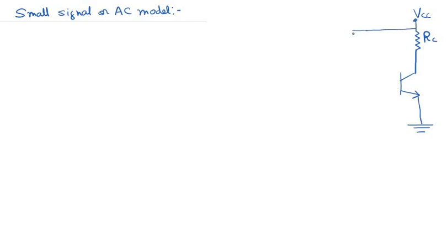We could have also done it with the voltage divider biasing scheme. There is not much difference, but right now we are showing this fixed biasing scheme over here. This is our base resistor RB, and just as before, the AC voltage is provided through a different path, where this capacitor Ci is present to prevent DC current flow into the AC voltage source.